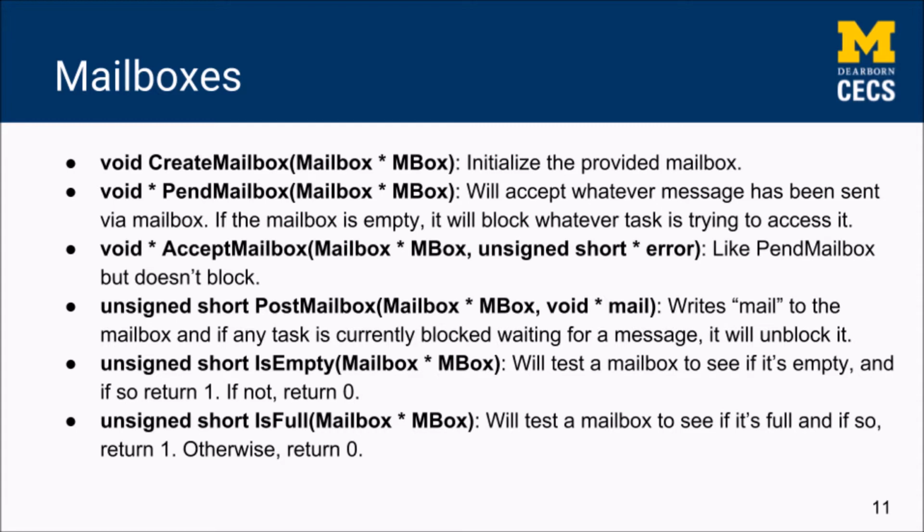So we then move on to mailboxes. We start, of course, with create mailbox, which will initialize the provided mailbox. We move to pend mailbox, which will accept whatever message has been sent via the mailbox system. Now, if the mailbox is empty, however, it's going to block the task that's trying to access it. Next is accept mailbox. It's basically a non-blocking form of pend mailbox. It's more of a query.